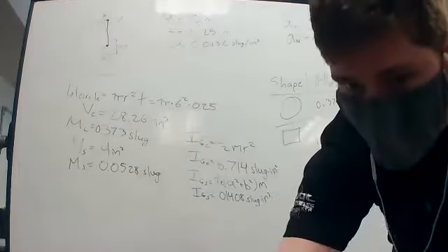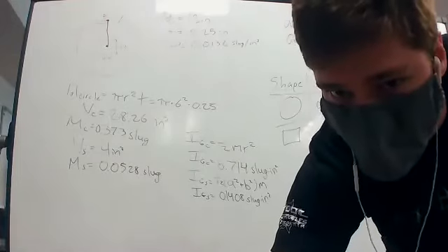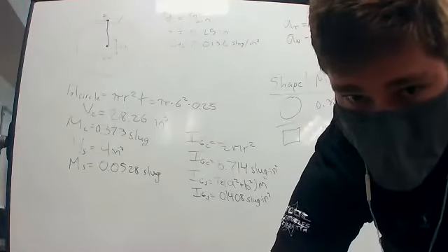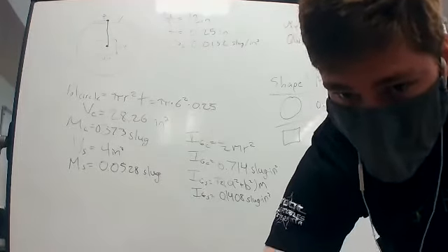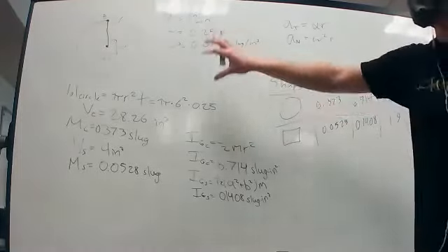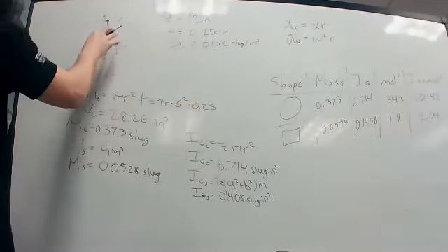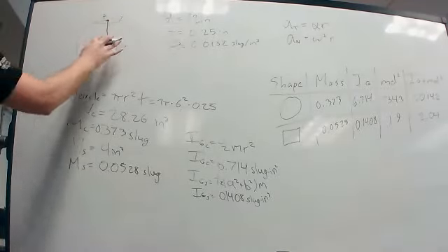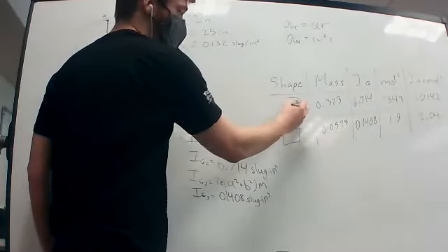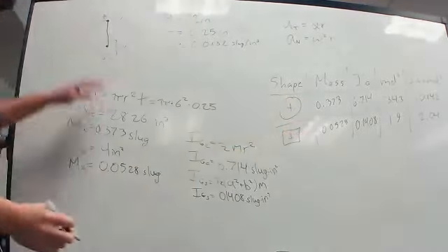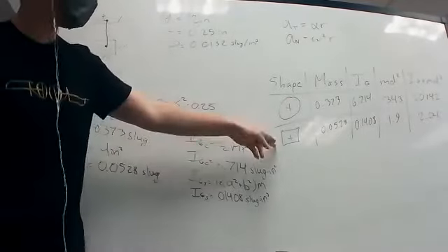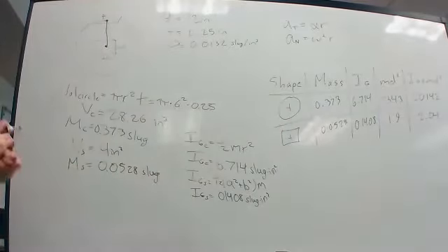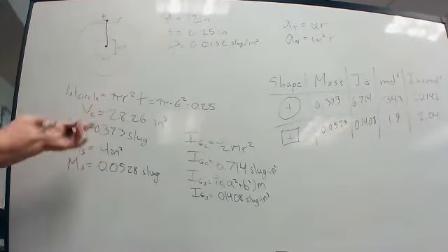So the entire question is asking us to determine the moment of inertia of this disk about an axis perpendicular to the page. The way this question works is that this square was not said to be a hole. This square was a plate on the circle. So this is an extra mass, so both of these are positive. If this was a circle with a square hole through it, then you would have a negative value on the square. But because it's two pieces that are fixed together, we have both positive.